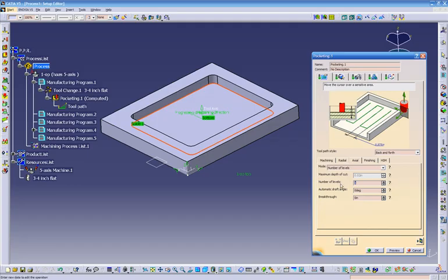So let's say we want to cut this 3 times, and let's make the depth of cut. We cannot select it right now, but if we change this to number of levels without the top, because we didn't select the top yet, we just put without the top right here. So now it's gonna tell us, okay, this right here stands for the thickness. So we put 200 over here and 3 times.